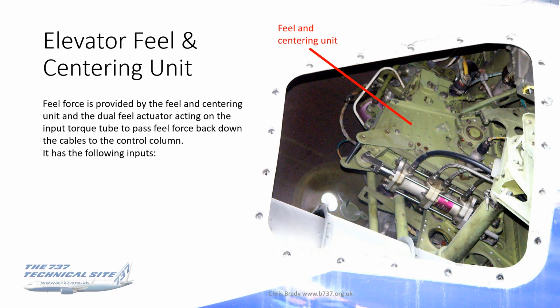Okay, so the elevator feel and centering unit. It's one of those blocks on the schematic in the FCOM. In actual fact, the FCOM schematic for pitch control is actually quite good. So you may be relieved to hear that I haven't done a schematic for this presentation. I point you in the direction of the one in the FCOM, because it does cover things quite well. So the feel force is provided by the feel and centering unit.